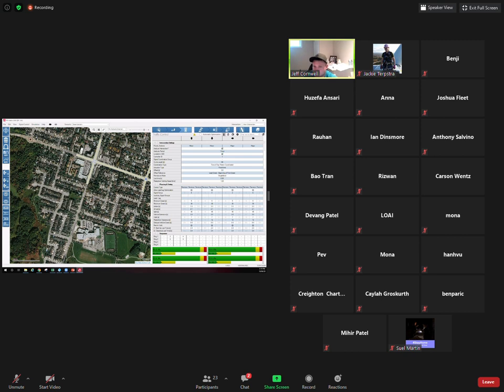And if I go over to Cortland, you'll see that right now it's not giving a lot of time on 2 and 6, but a lot of time for 4 and 8. So again, if I click on this button here, optimize split and cycle time, or optimize split, because I don't want the cycle time to change, I can click optimize split. And for some reason, it didn't change anything.